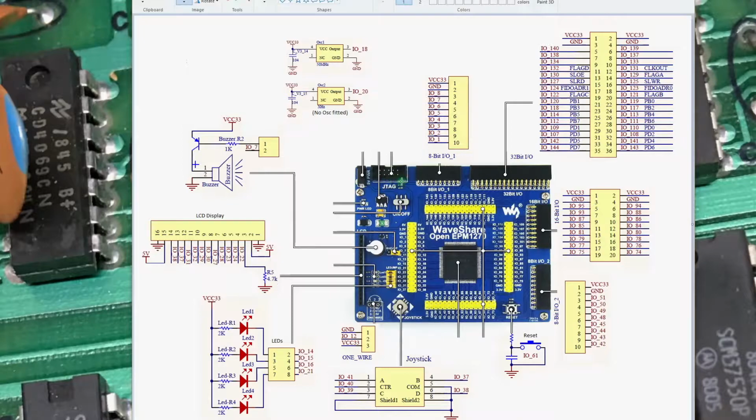You've got the JTAG interface we talked about on the main schematic where your USB Blaster comes in and connects. And it's got 4 pins that come back to the device that take control of the device and do the programming of it.